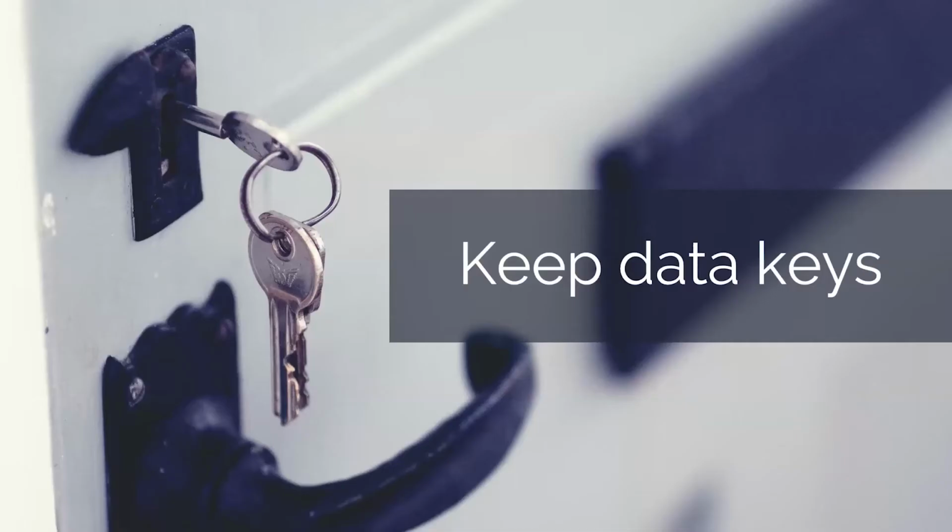And keep data keys. Often, particularly in databases, but even in spreadsheets, you're going to use abbreviations. Make sure you maintain a list of what those things mean. We did work with a utility a year or two ago that had a couple of decades' worth of break data, and they had 30 different codes for different kinds of breaks, but they'd lost the definitions for the codes. So what could have been a really robust analysis was significantly hampered by the fact that we didn't know what any of these codes meant, and we could only essentially know that a break had happened and where it had happened.